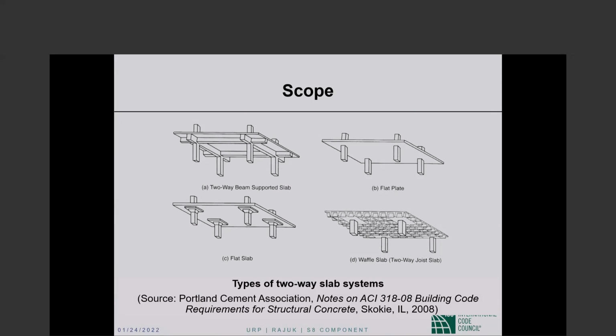Now, obviously, we do not cast a solid slab and then remove the tension concrete. There are ready-made formworks available for rent around the country that will produce that structure for us. This is called a waffle slab because it looks like the waffles that we eat. Notice that the slab around the column is not ribbed, it is solid. And that again is because of punching shear.